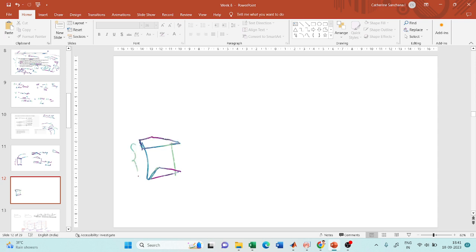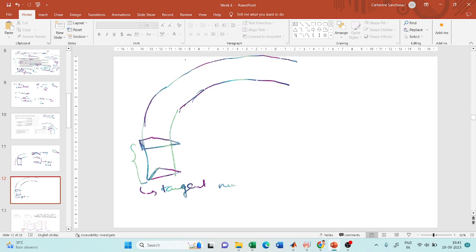Okay. So this distance that is required is called the tangent runout. During this tangent runout, your section will be straight. It will not have any transition or any curve. Now, there's a change of alignment, and after this, you have your curve. My curve starts only at this point. So this is my horizontal curve.